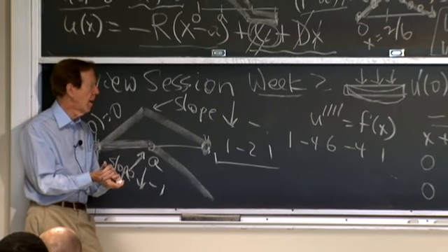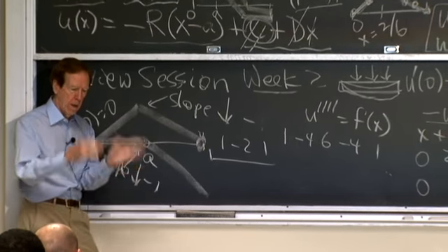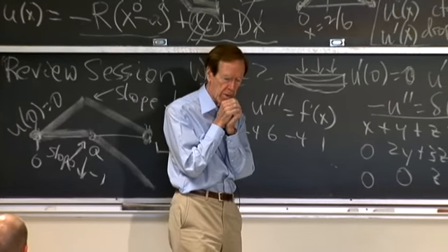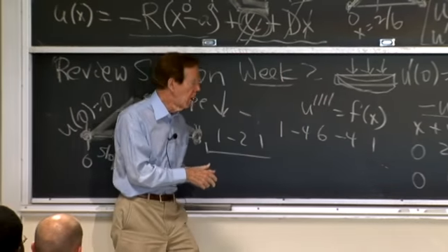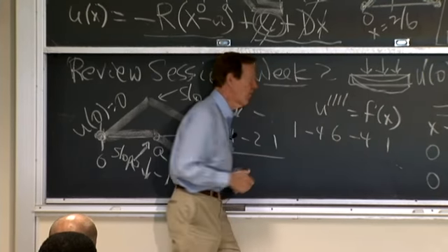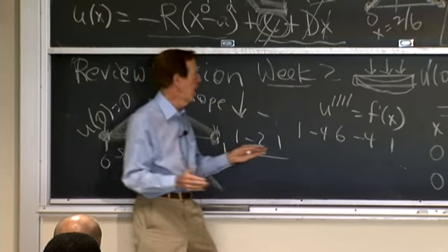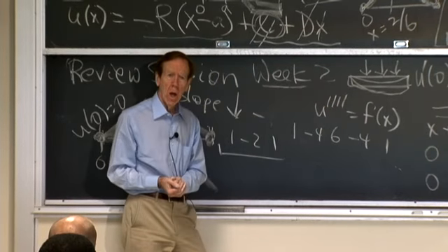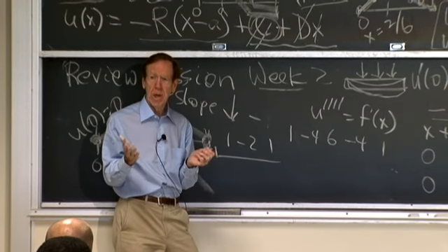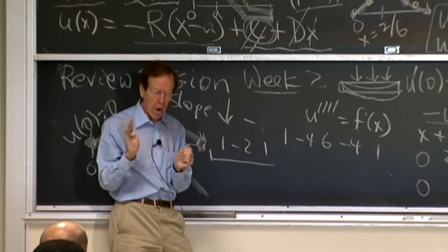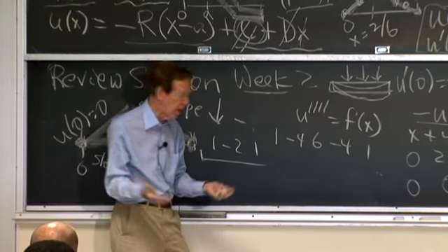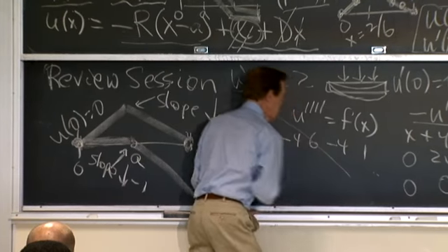And what's the deal with boundary conditions? What are you figuring on beam problems for a fourth order equation and a matrix that's stretching out further? What's going to happen at the left-hand boundary? I guess my specific question is, how many boundary conditions do I now need? 4. And the typical is 2 at each end. That's the balanced way. That's the way that would make this matrix sort of symmetric.